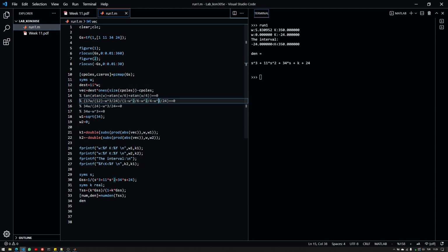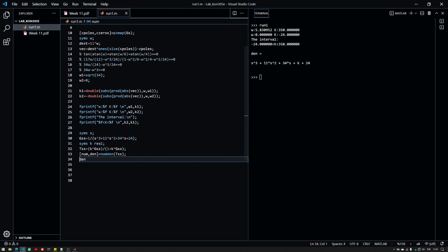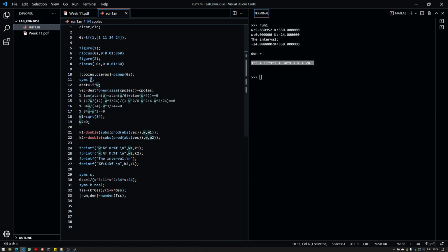That is immediately obvious from here, but there's also a method that is very similar to the root locus determination here, namely the following. You can go ahead and assume that if this is the closed loop, and if you know that there is a crossing at j omega, you can basically use this j omega, which should be the root of this polynomial, plug it in, then equate it to 0, and then find a solution for omega. Because if this is a root of the closed loop, and this is a characteristic polynomial of the closed loop, this means that j omega should satisfy this polynomial.